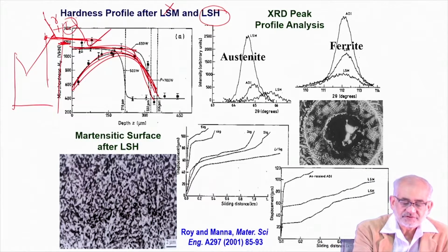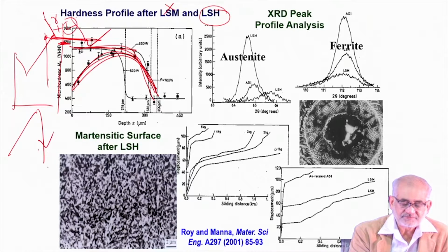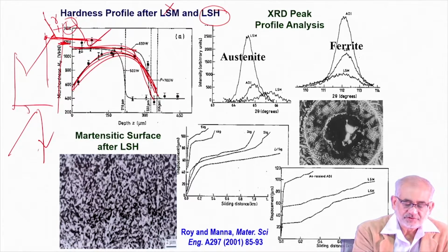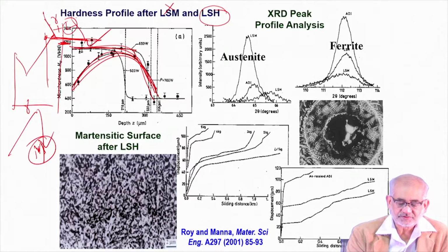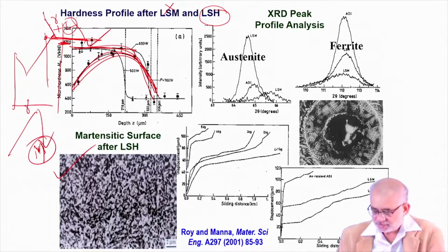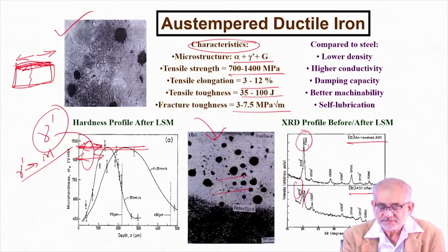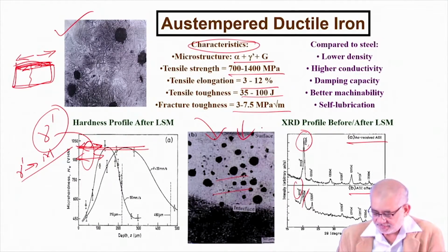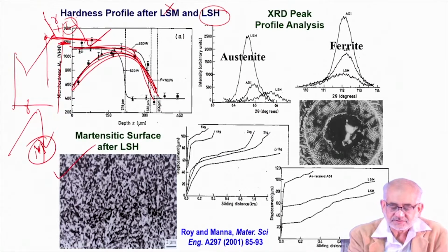So in the process, when you heat and then quench by self-quenching, you convert this to austenite, and by self-quenching, you convert this austenite into martensite, and that's what you want. So this is exactly the kind of microstructure that you develop. Compared to this microstructure here, if you develop this kind of microstructure, it is predominantly martensitic.